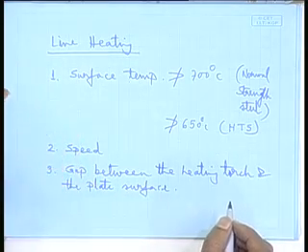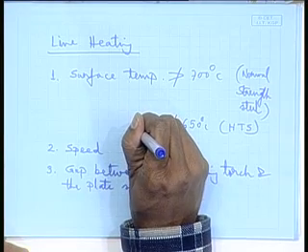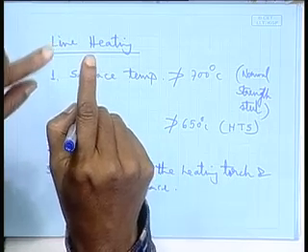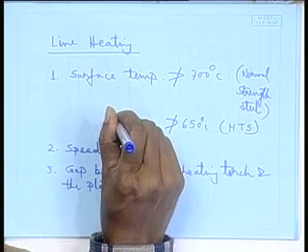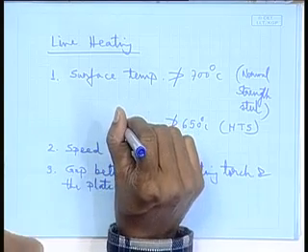Suppose we are heating by oxyacetylene flame. The plate is here. If I keep the flame tip here and move it at a certain speed, I attain a certain temperature. If I bring it down and do the same thing, I attain some other temperature. Obviously, bringing it down I will have a higher temperature, but if I bring it very close, again it will not work. It depends on the flame characteristics. So this gap is important, depending on what kind of heating source you are using.